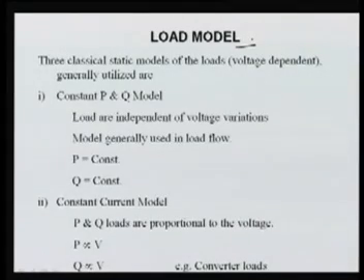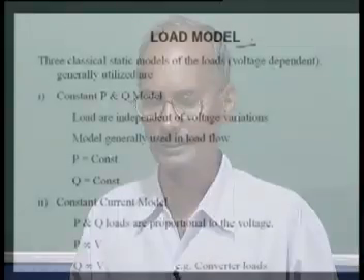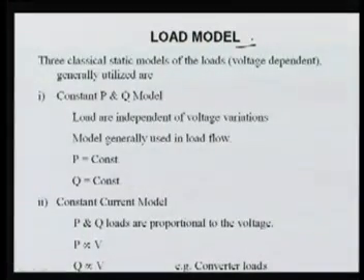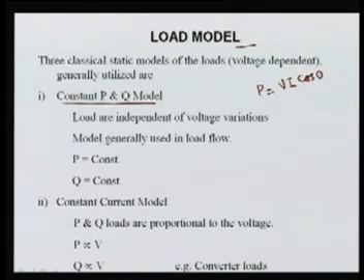So let us see the load model, and that load model is also included in the transient stability program. As I said, the loads are represented by impedance or voltage dependence, or the dynamics of the load must be included in the transient stability program. There are 3 classical static models of load, that is voltage dependent, generally utilized. The first one is your constant PQ model. We know P is nothing but VI cos theta, where theta is your power factor angle and cos theta is the power factor, as we know.